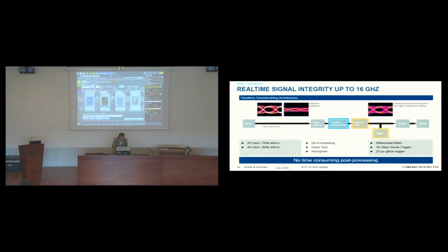Okay, I will remove. Or this option here, probe cable, is when I want to measure the S parameters using the pulse generator included in the oscilloscope. I can calculate these parameters using the pulse generator as a TDR response, and then converting this to S parameters. So what I will use instead is just the model I have, just to make it quicker.